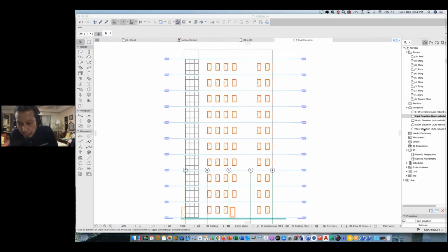So this is pretty much what we had to show. Is it, Zait? Do you have anything else? Yes, basically I just want to show how you manage modules for your typical floor. You can also have typical 1, typical 2, in case you want a different design from second to fourth or fifth floor, or maybe the top. As long as you understand how to manage the module file, you can do as many typicals as you want. Then I'll show you how to create a complex profile, simple ones like the groove example, and also how to do a railing that is fixed to the wall.